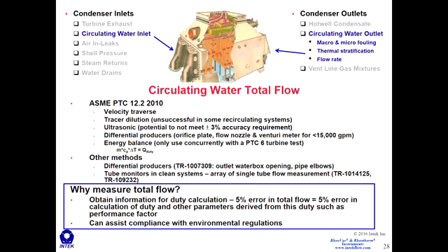You have to be careful here because you have to get the chemistry right to make this measurement come out right. Sometimes the chemicals used for the tracer can actually react with some chemicals in the cooling water, so you have to be careful about that. But it's a good method to measure cooling water flow.